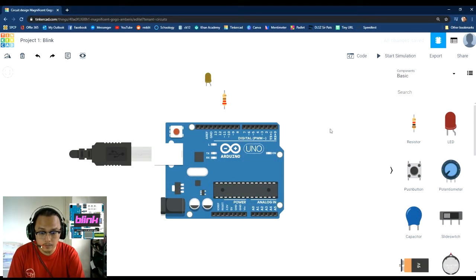All right, quick question. Why do we need resistors? Again, LED are light emitting diodes, so they convert electricity to light, but then that electricity has to be controlled. So for an Arduino board, usually it provides 5 volts. So that 5 volts is kind of big, all right? It will overwhelm the capacity of the LED.